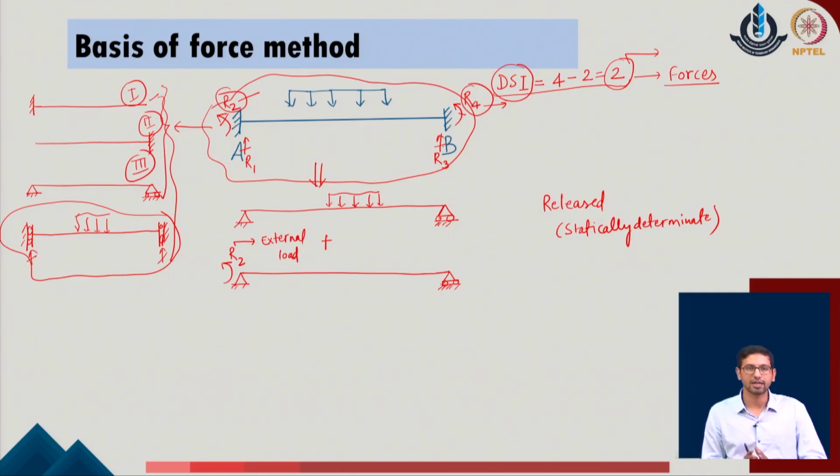So, the idea is that we will be considering some of the reactions which are over and above the degree of static indeterminacy or the available equilibrium equations. We consider these forces or these reactions as the unknown set of forces in the given system, and we remove them from the basic system initially, and we consider them as the external load active on the statically determinate system.